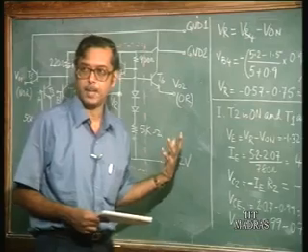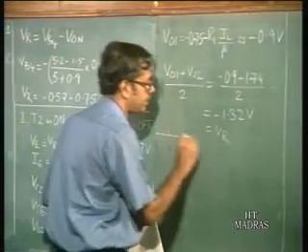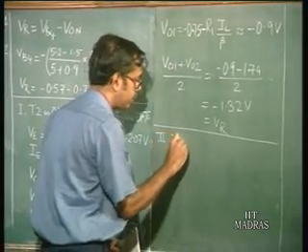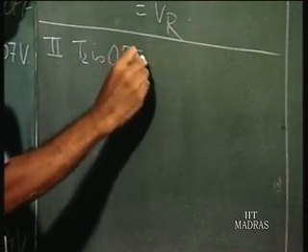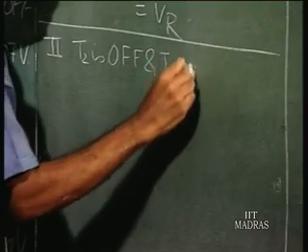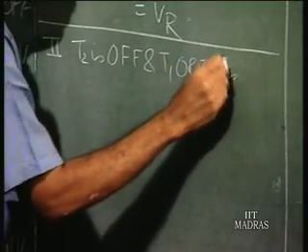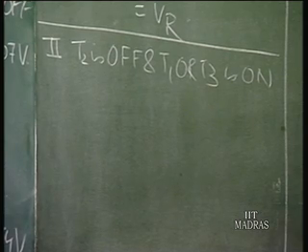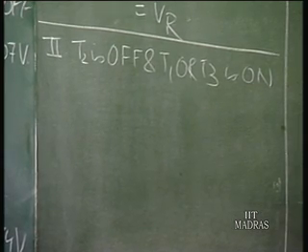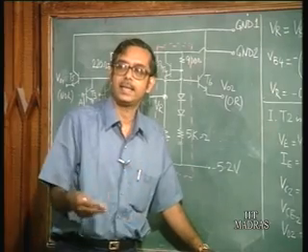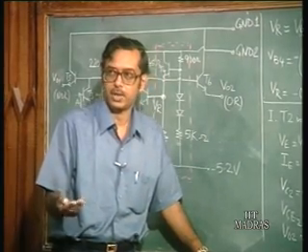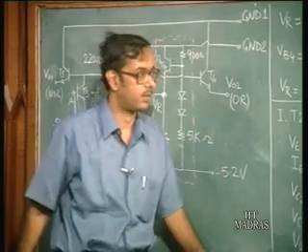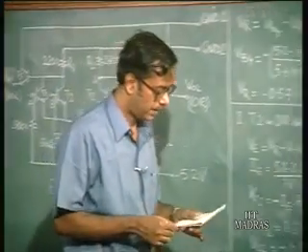That is case 2, T2 is off and T1 or T3 is on. That is, the base voltage for transistors T1 or T3 is greater than the reference voltage, which would mean that either T1 or T3 is on, whereas T2 is off. So, if you have this condition,